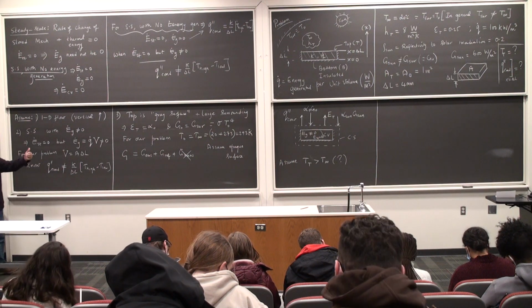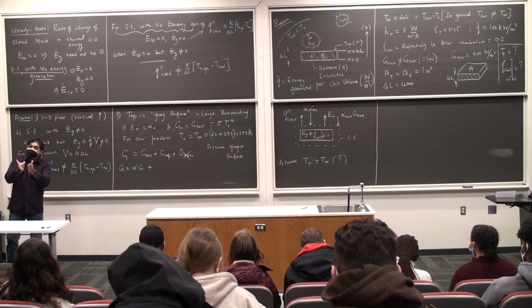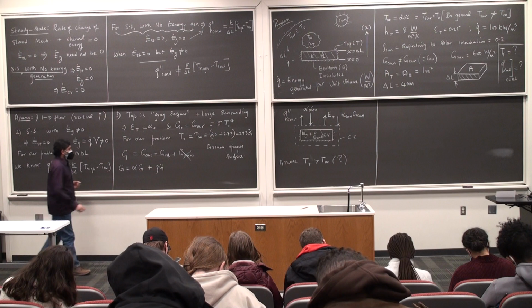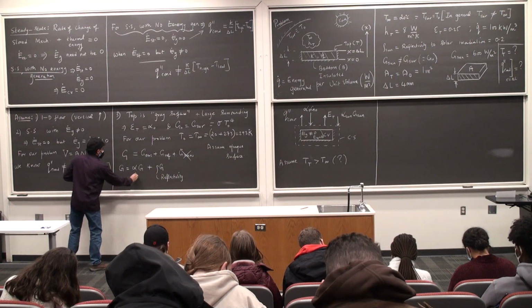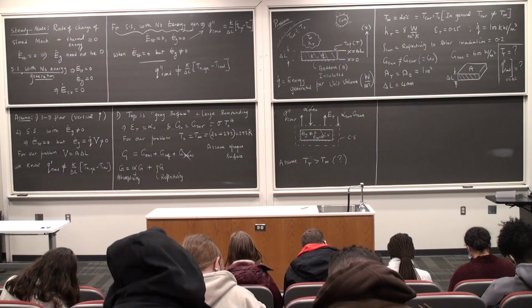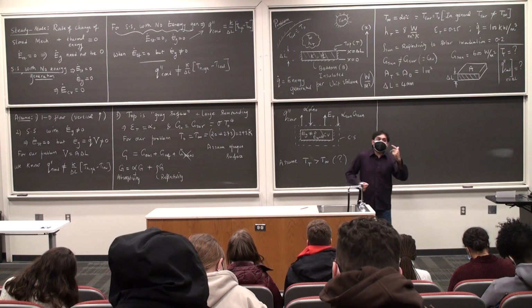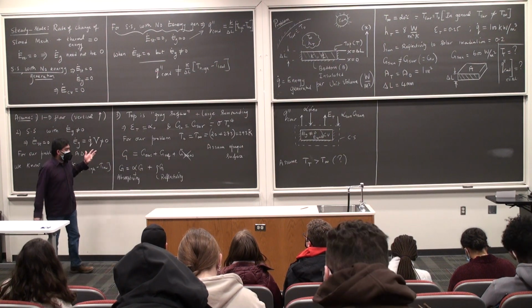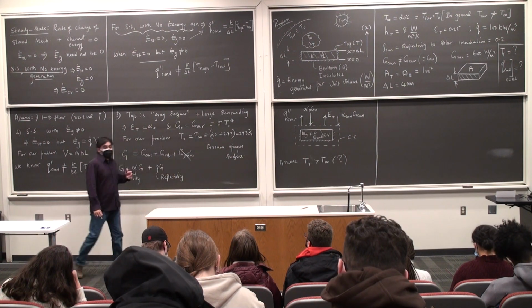G absorbed, I write it as alpha times G. So capital G is alpha G, which is the portion that is absorbed, a fraction of the irradiation absorbed, plus rho times G, where rho is the reflectivity. So this is reflectivity, this is absorptivity. So three things that happen for a surface, actually four. There is emissivity, which has nothing to do with irradiation. There is absorptivity, there is reflectivity, there is transmissivity. We don't have transmissivity, tau, because we don't have any transmitted radiation, which is due to the fact that we have an opaque surface. But we do have the other two.